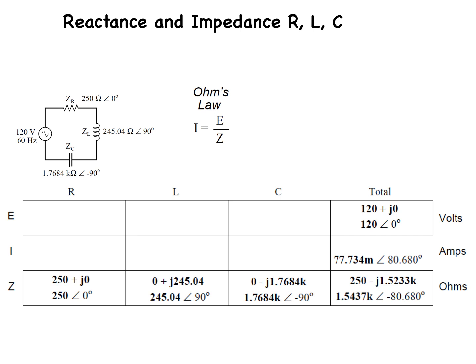And we're going to use that total impedance now to calculate the total current for the circuit, and we're going to use Ohm's law, which means it's just the total voltage over the total impedance of the circuit. But we have to remember that we are using phasor notation, so it's going to be the 120 volts all over the total impedance for the circuit.